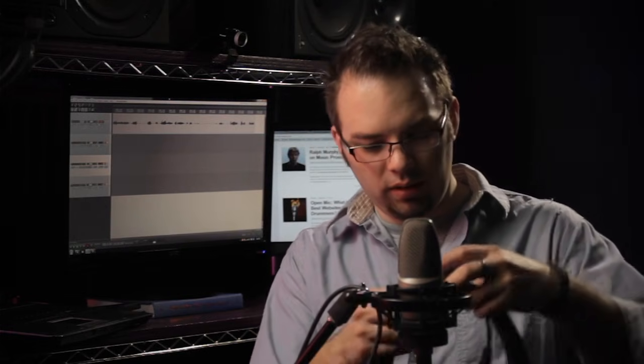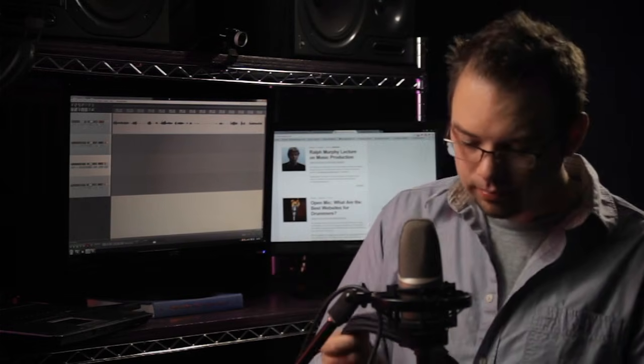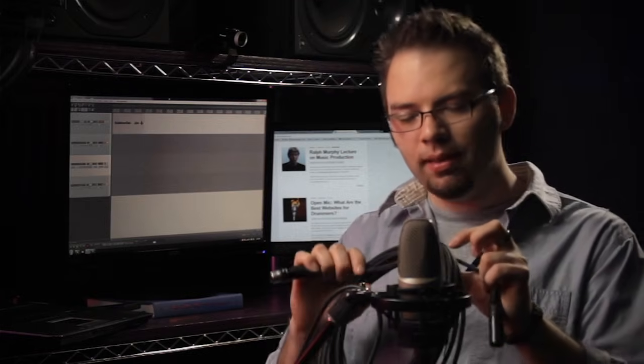Now, it's really, really important that when you secure this cable, in this case I'm using a Velcro strap, that you keep both ends of the cable on opposite sides of the coil. And you want to keep them on the same sides as you coiled them. And the reason is, if you accidentally pull this side underneath the cable, you will create a whole bunch of knots, literal knots in the cable. And that can be annoying as well.